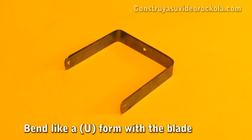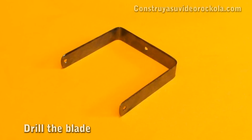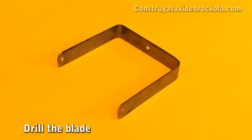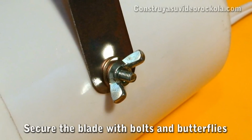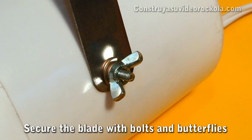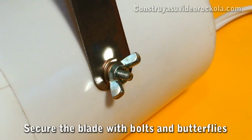The metal sheet will serve as a strobe support; bend it into a U. At each end, make a hole using a drill bit of the same diameter as the screw that attaches the sheet to the jar. We make a couple of holes on the sides of the jar and put the screws in, holding them with washers, leaving the butterfly nuts on the outside, so you can adjust to your preference and change the angle of the strobe.